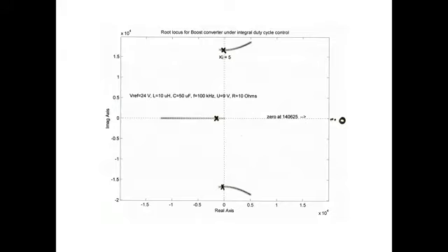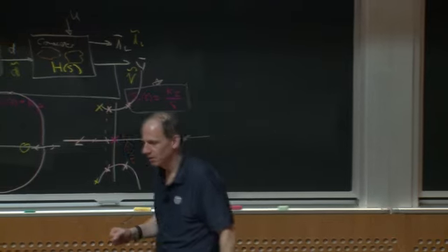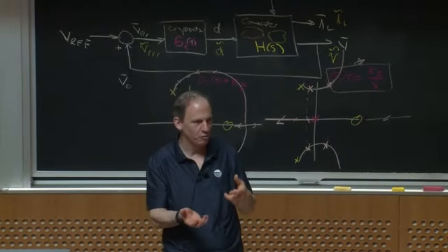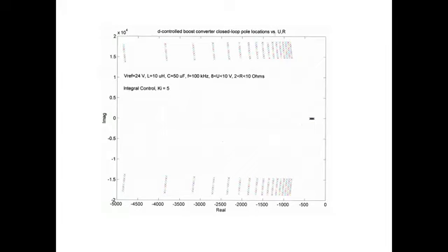I could then say, all right, let me calculate the closed loop pole locations. That's how, once I have the feedback loop, if I kick the output, that's how it'll oscillate once it went with my control system in place, okay? And I could calculate that for every possible value of R and input voltage that I might deal with. And if you do that, this is what you get, okay? So you could argue that no matter what, it's at least stable, right? All the poles are in the left half plane, right? This is the j omega axis on the right here, okay? And I'm going to have a dominant kind of first order pole, and then some lightly damped higher order poles.